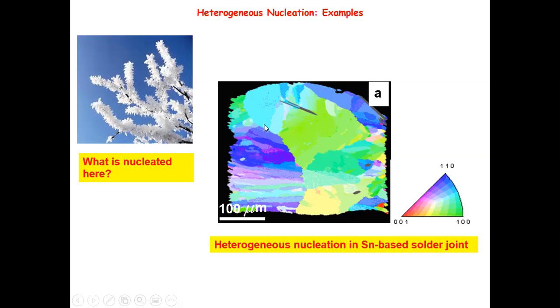So this is a very interesting example of heterogeneous nucleation as manifested in the microstructure. And clearly, which is out of the scope of this class, if you have grains in this direction, this can significantly change the conductivity of the material and also change the mechanical properties, such as resistance to impact. So heterogeneous nucleation is indeed very important, and this is not a good microstructure, so we have to find a way to control and optimize this. But again, this is a good example.